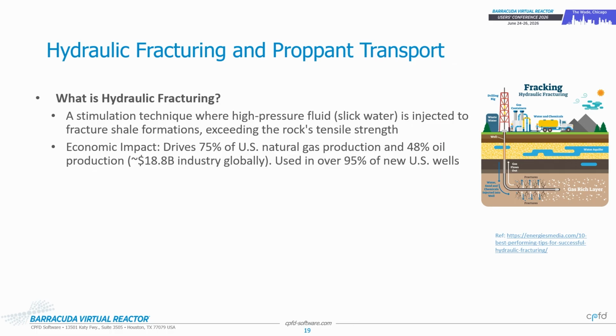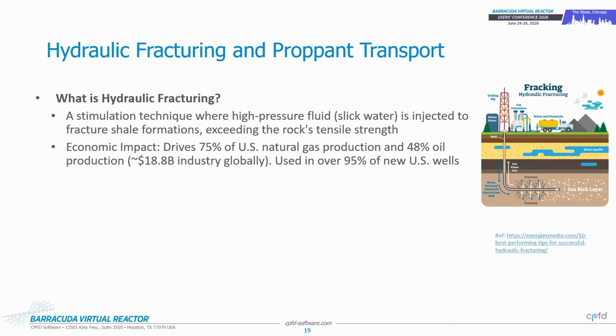You pump in high-pressure fluid, which is essentially water mixed with some kind of polymer. It's called slick water. It's highly pressurized. You initially blast some perforations, literally blast them, and then you pump in this high-pressure fluid through that, right? And you can imagine it creates hundreds or thousands of these fractures into the shale formation. And then once you do that, you provide interconnected pathways for the oil to flow through. But is pumping liquid just good enough?